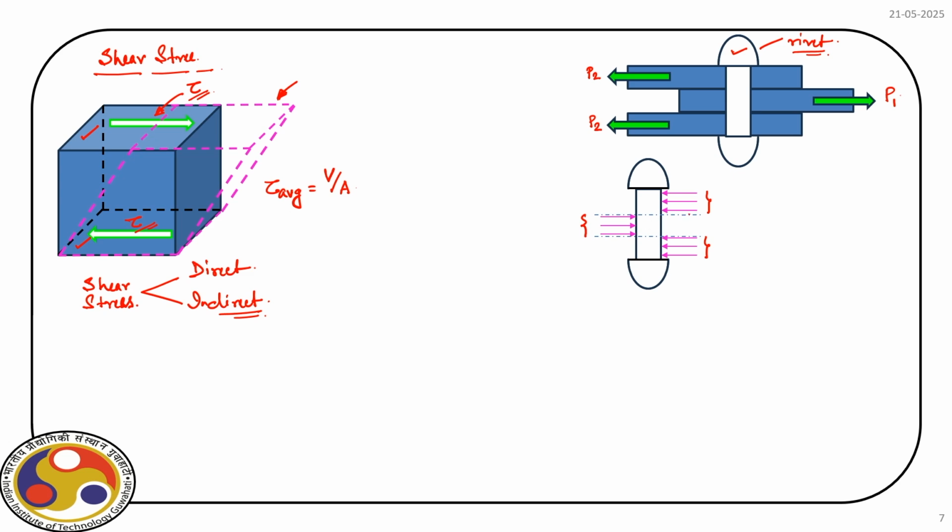Now, if we consider a section, say this segment, and then draw the free body diagram, then obviously we have the stress here, and because we cut along these two planes, obviously we will have shear stress developed here. If we look at the plan, again it is a circular section. Obviously, over the entire cross section, we have this shear stress acting.